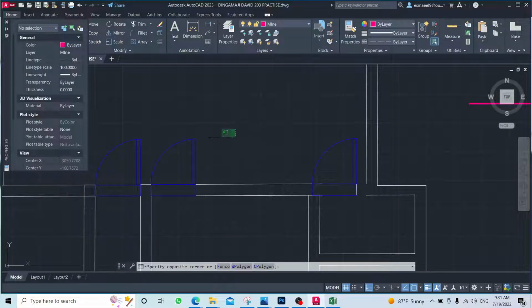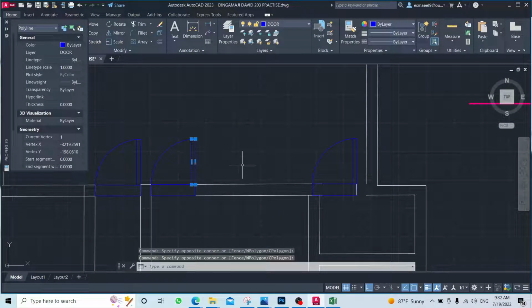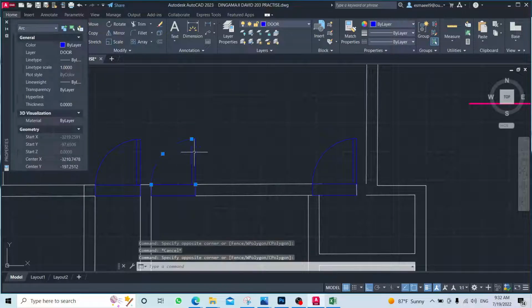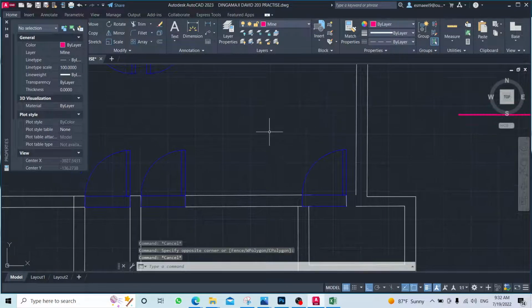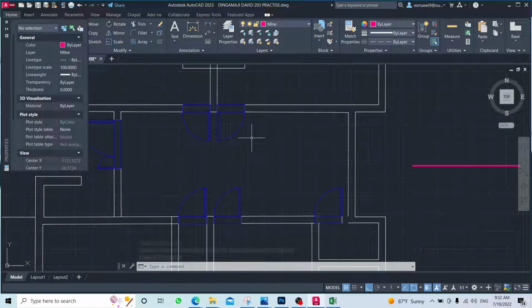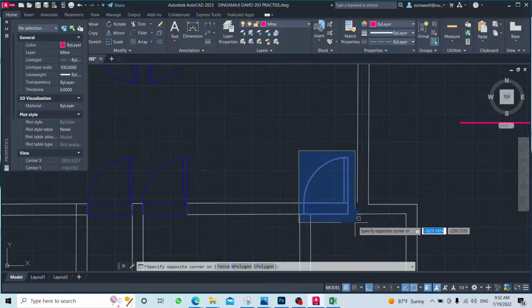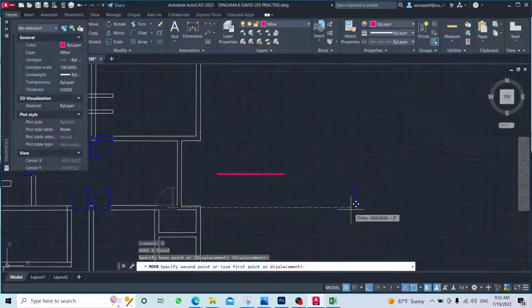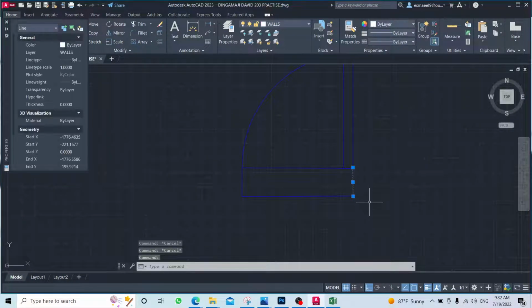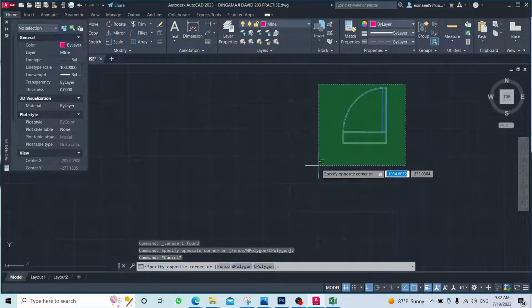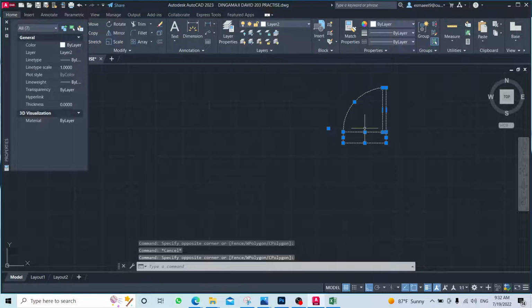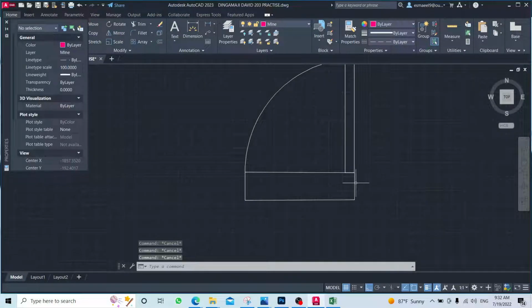Something else. Look, if I now select one of them, I can see this is a piece, and this one is a piece, and this one is a piece. This is not the thing I want. We talked about the join command, right? Join. We talked about J, right? Let me move. At the beginning I will delete this one. Now I will try to join all of them. I will first move them to layer 2 to be able to see them very well.